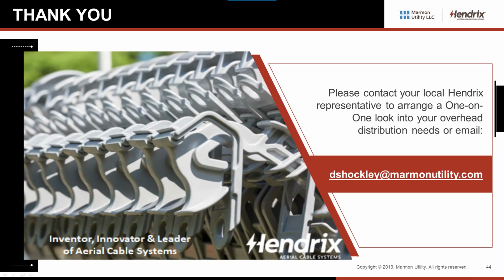So it's very distributed weight. It's under very low tension. So we don't necessarily worry about the size of the conductor depending on the span length. Again, it's all 30-foot spans. Now, we realize there's more surface area on the phase conductor, so it will pick up more ice and there's more wind loading, but we take all of that into consideration when we're doing our engineering calculations, and that's really only going to affect the size and the tension on the messenger.